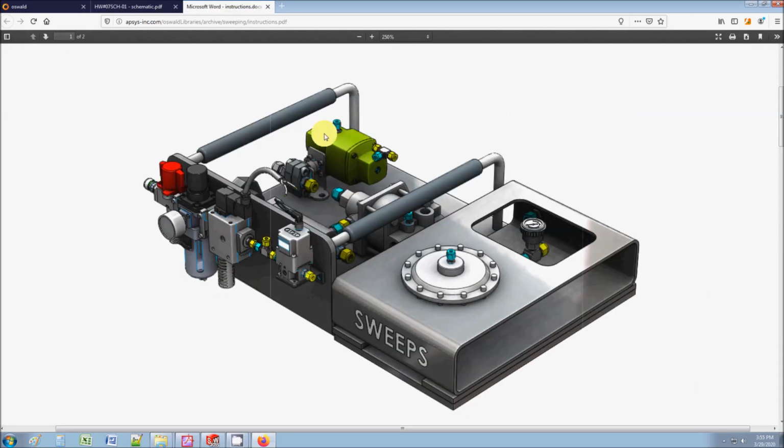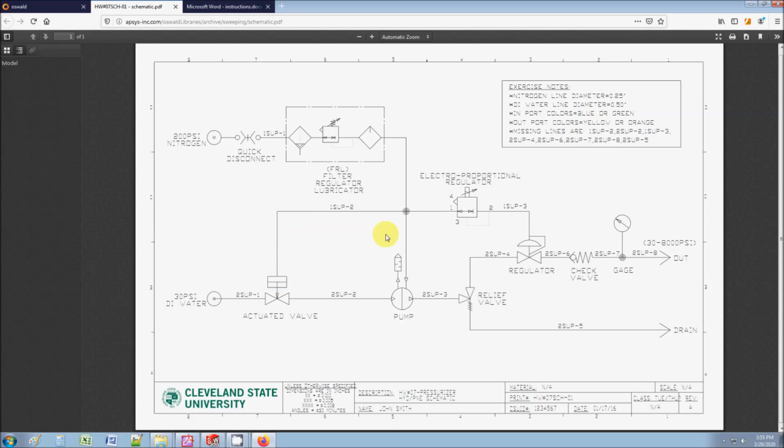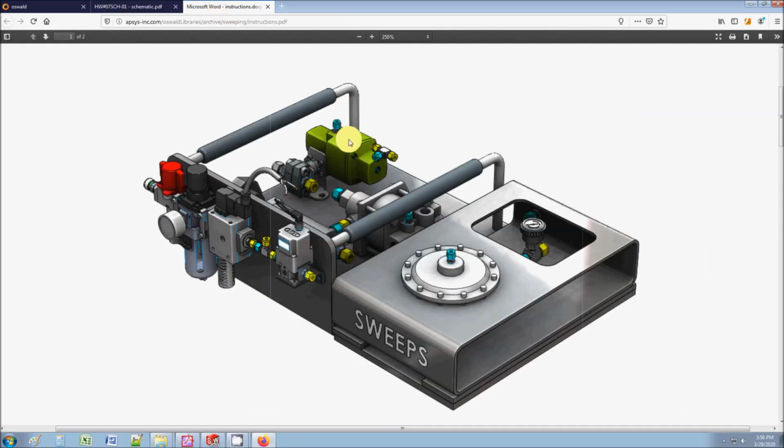Also, what you'll notice here is an actuator. This is just a valve, a ball valve, like we've already talked about, but it's got this weird actuator on top. Reason for that is because it's automatic. It's not those manual valves where you can move it with your hand. This is actuated with air. So when you energize air into it, all right, it will either turn on or off. Okay, so it's just a fancy large device just to turn the valve on and off, and it can be controlled through a pneumatic system that's controlled through a manifold and through the PLC.